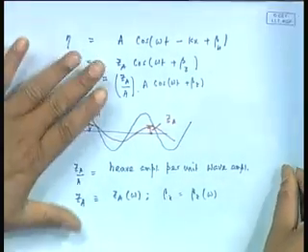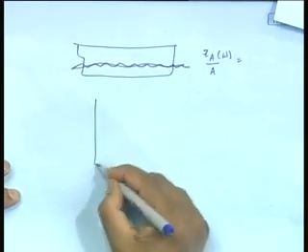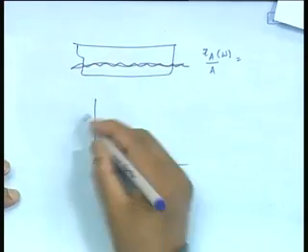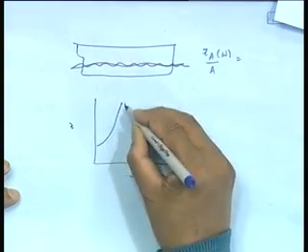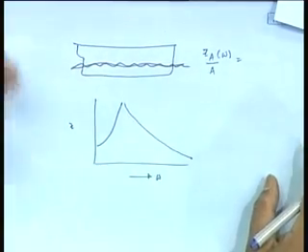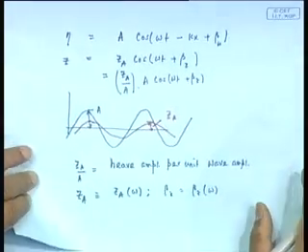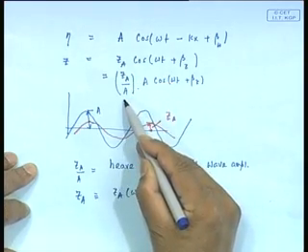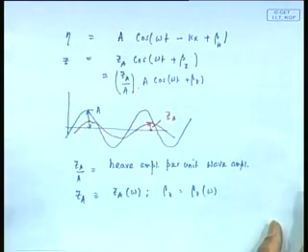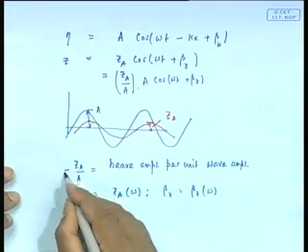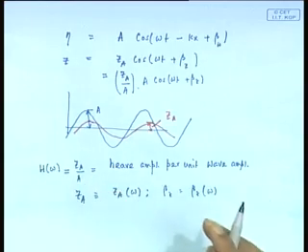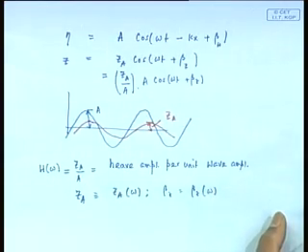In fact, there is a more interesting way of putting that. If you remember our regular wave response, what did I find out? Omega versus, you remember, here I have got this Z, and how did it look like? Obviously, the very graph showed that how much it responds depends on omega. So there is no question or doubt on that fact, you see. So this ZA by A, my amplitude of response by amplitude of incident wave, you can call transfer function, or I can call this to be, say, some function h. Obviously, it is a function of omega. What transfer function essentially implies is output by input, yes, output per unit input, but it is a function of omega. That is what I was trying to tell here.